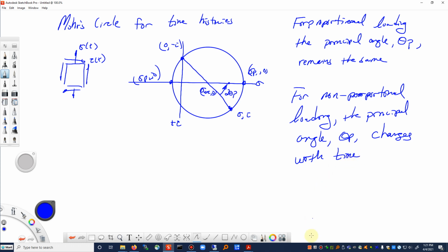And this gets to be a little bit more challenging when you think about what's happening in the material. So if we were to take a look at a stress block and the principal stress directions at one instant in time were off in this direction, and cracks were forming perpendicular to the maximum principal stress here, or they wanted to form, or there was damage occurring to that plane, then at another instant of time, the principal directions change down this way.